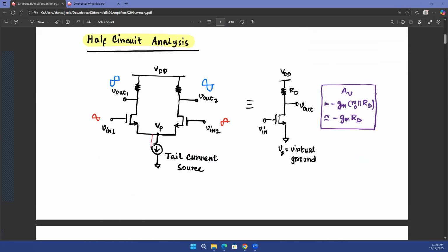Yes. So you know that a MOSFET is basically a current source. If the MOSFET is in saturation, the MOSFET is a current source. Okay. So you can bias this MOSFET in saturation. So that will make it a current source. Or you have already learned about current mirrors. So you can mirror an external current and put it over here to a MOSFET, and then connect the drain and the gate of this MOSFET together. And that will make sure that the current flowing here is the same current that is flowing here if the W over L ratios of the MOSFETs are equal. So this is the way people actually implement this.